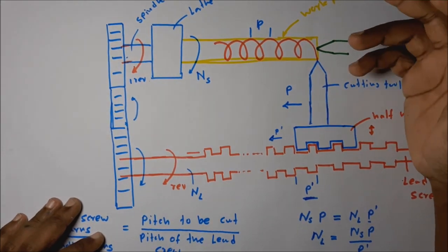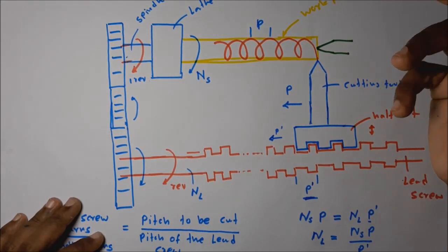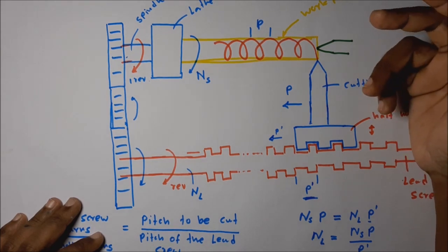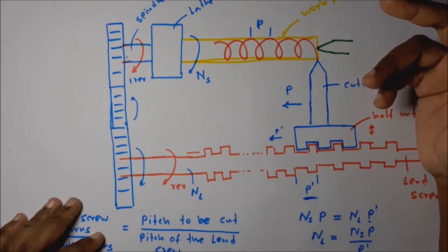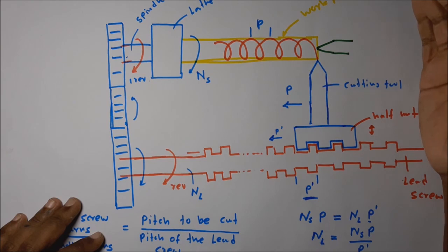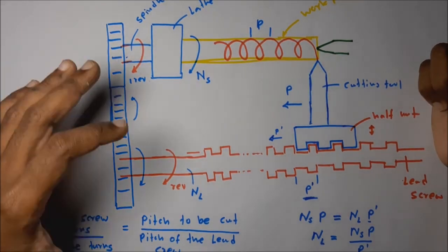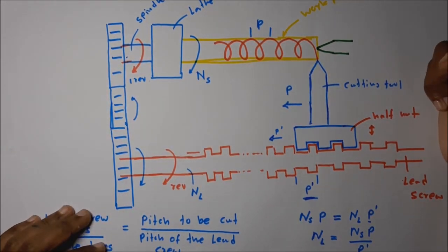That means with the lathe machine, a set of gear wheels comes with it, especially in older type lathe machines, starting from 20 teeth up to 120 teeth in 5-teeth intervals. So let's see how to obtain this gear ratio from these available gears in the next lecture. Okay, thank you.